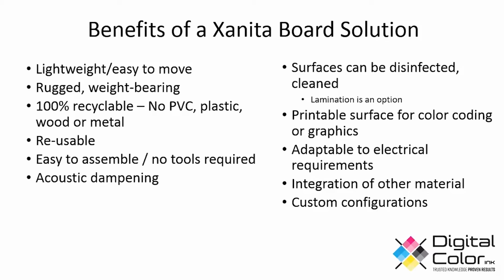Also, it looks like we have a question with regard to LED lights. In particular, with the rooms that are being created, is it possible to mount an LED light directly to those walls? Yes, you could mount them to the walls, or you could embed them in the walls. What I mean by that is in the surface, you can cut out a spot, put your LED structure in there, and then run the electrical in between the walls and out to the electrical. So there are different ways you can integrate LED lighting into Xanita board structures.